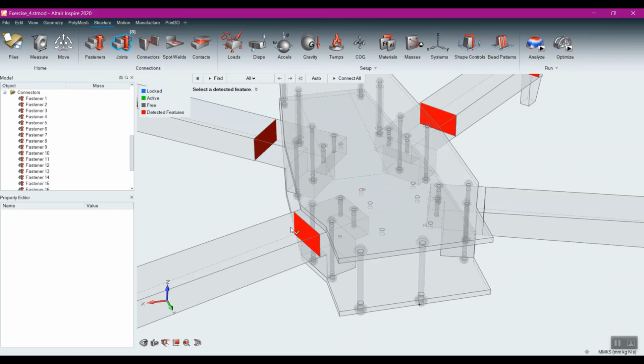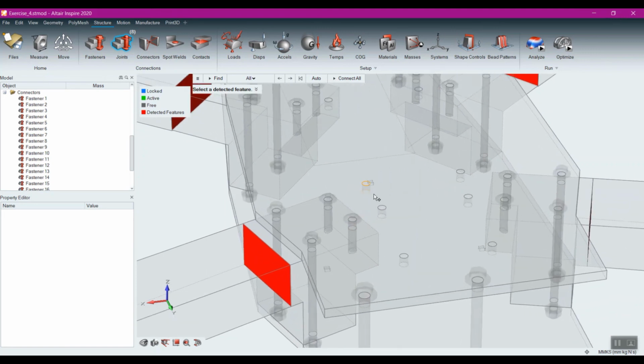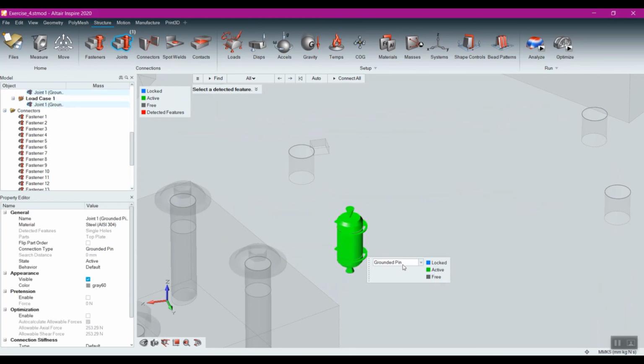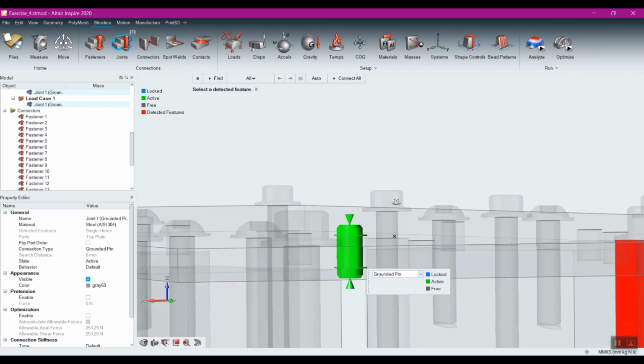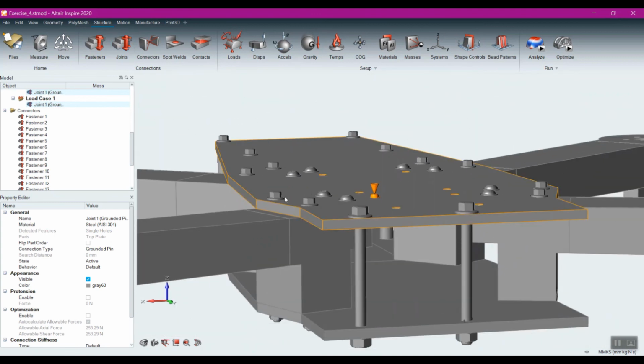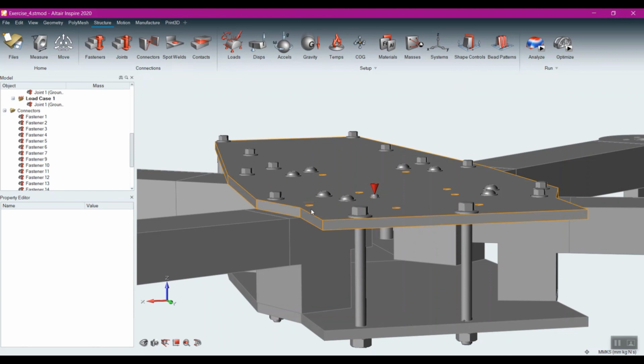You can see it's detected these four planar joints, but primarily these are used in the case of holes, and it allows us to create pins, and we can create them as either just a sliding pin, which won't have these clips on the end of it, or just a regular pin which has the clips on the end of it. So if I had multiple, in fact, let me do this. Let me get rid of, say, this one right here. And we'll come back to the pins here.